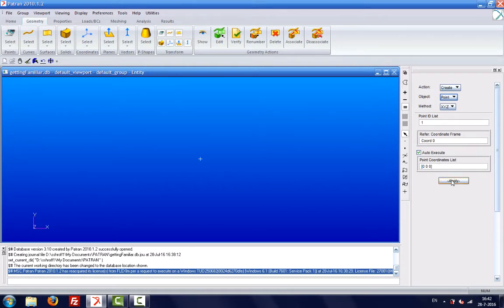And unless and until you press apply, it's not actually going to carry out what you asked it to do. So you must make sure that after you have selected all the things in this list, you must always hit apply. And sometimes the apply button is actually lower, hidden underneath. You have to make sure you find it and click apply. Otherwise, the options you chose will not be applied to your model. So you can see there are all different kinds of geometric analysis. It's just a drawing tool. You can, of course, draw your models in another software and also import it. That's possible. Sometimes it's allowed in certain particular file formats, so you have to be sure that it can be imported into your particular program.